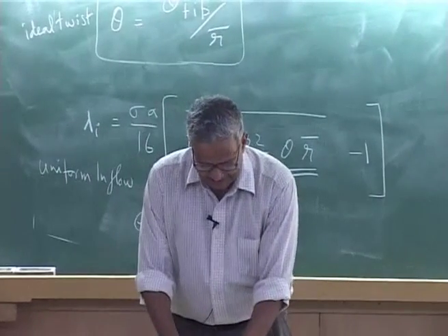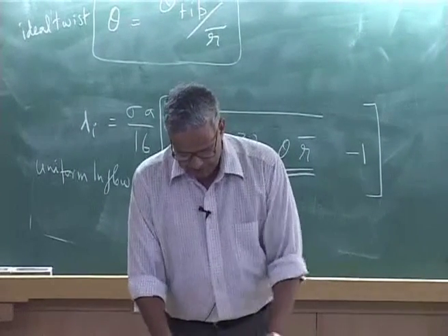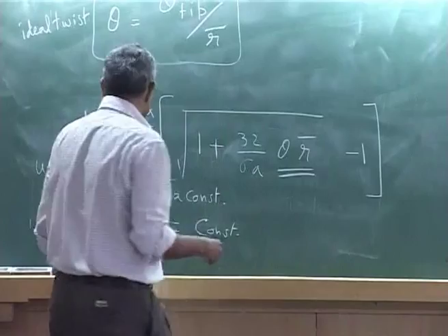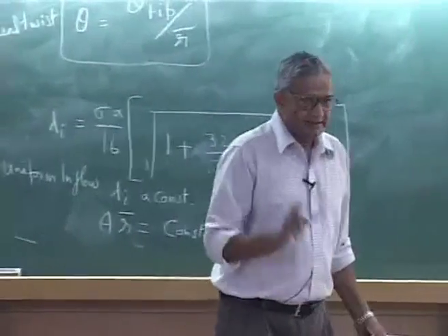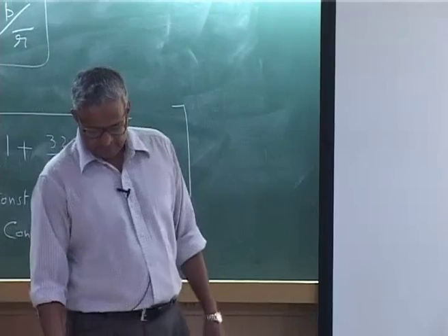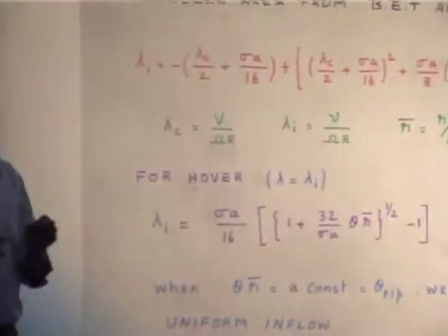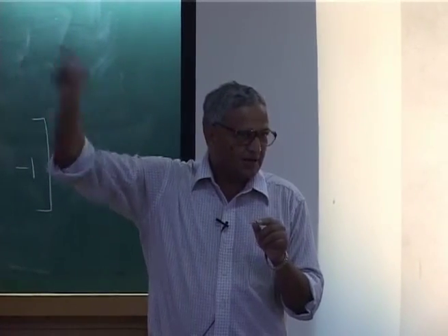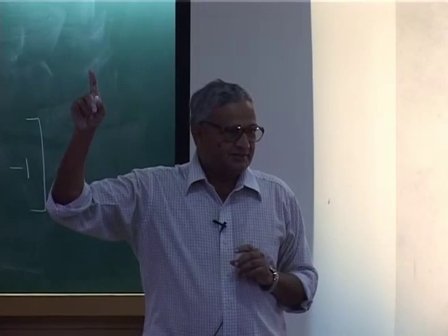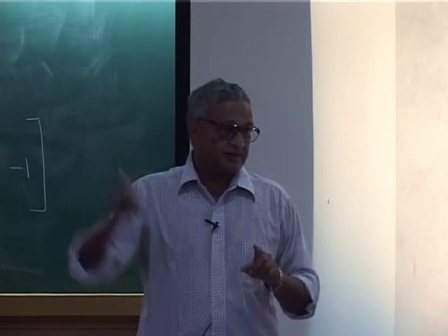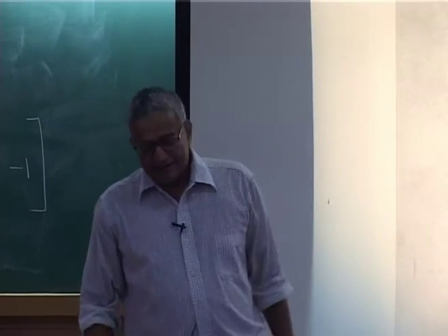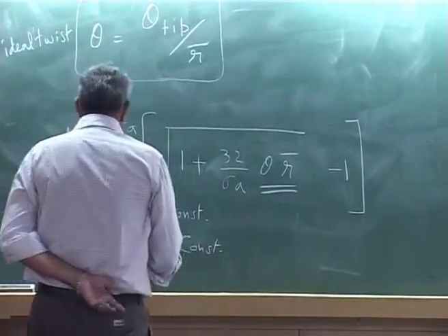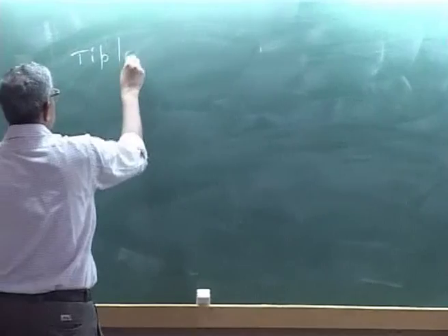There are certain other important points. I will just briefly mention two of them now before I leave you. I mentioned that the tip region, the lift as what we saw, it goes like a parabola to the tip, r square, but then near the tip region the lift is actually 0, it is not a high value. So, there is a drop. Now, there is a correction you have to give. This is called the tip loss,